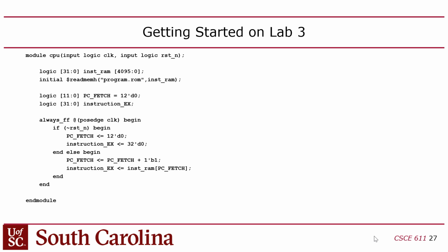So if you're debugging, you put your cursor down, PC fetch might be 12, right? It means you're fetching instruction 12, but the instruction EX is going to be 11, right? It's going to come because 11 was before 12, and so that's further along in the pipeline, right? Now you can imagine if you had a 5-stage pipeline, every signal would belong to one of 5 stages, right? That would get complicated. It's doable, but we wanted to simplify it a bit, right?